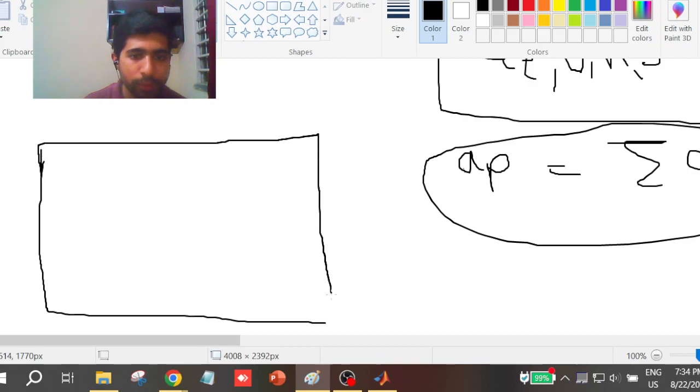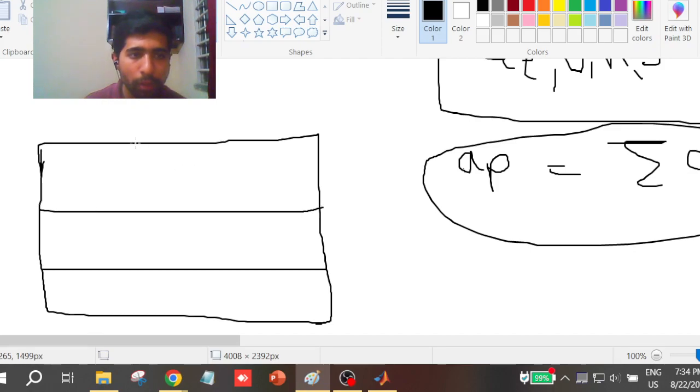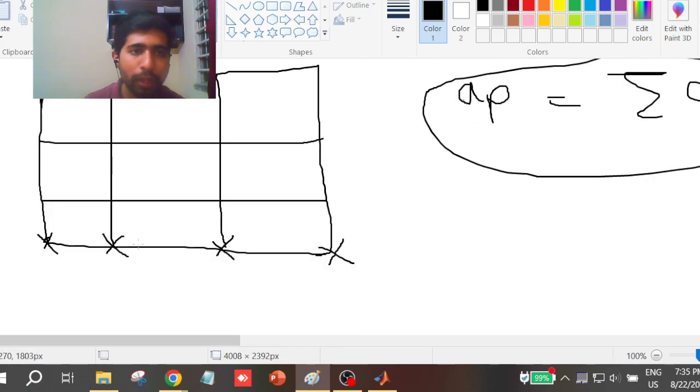My strategy is something like this. You can have a different strategy, no problem. This is what I am more comfortable with. So if this is my domain and control volume, I do define x and y values here first. This is easy to generate. For example, if I have 3 control volumes, I will get 4 corner grid points, something like this, whatever I have marked as x. From these I just call it as x and y, in general. In my code also you will see like that.